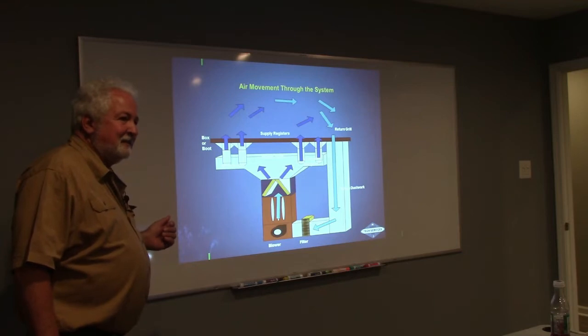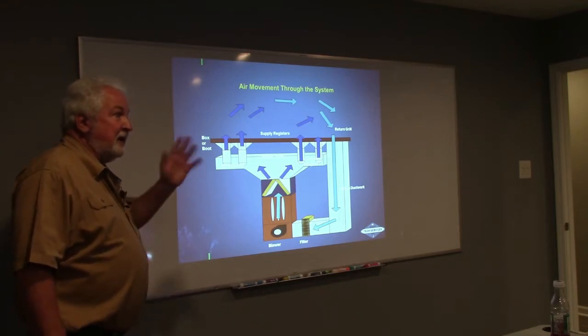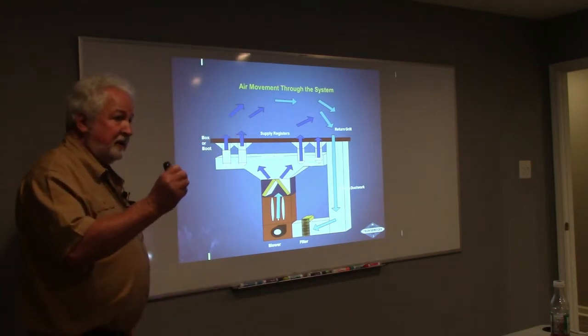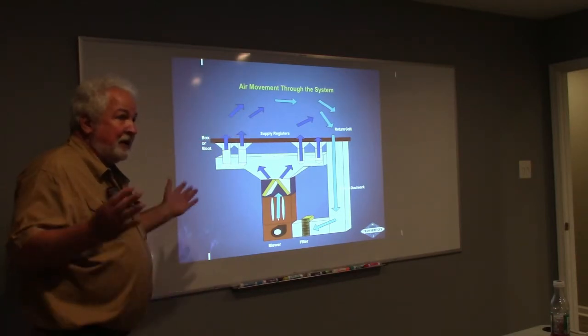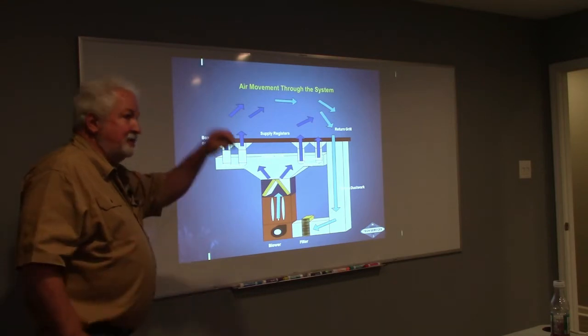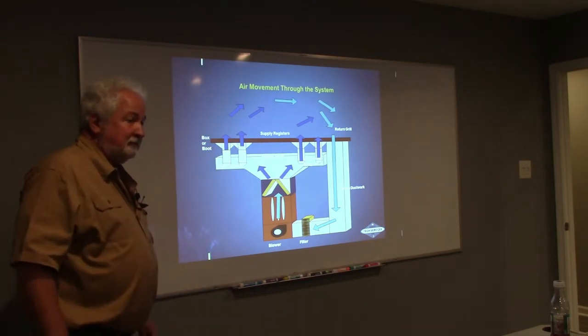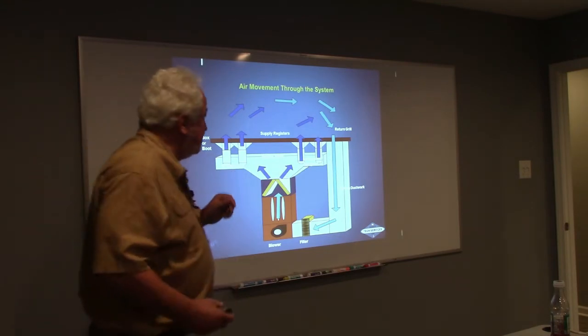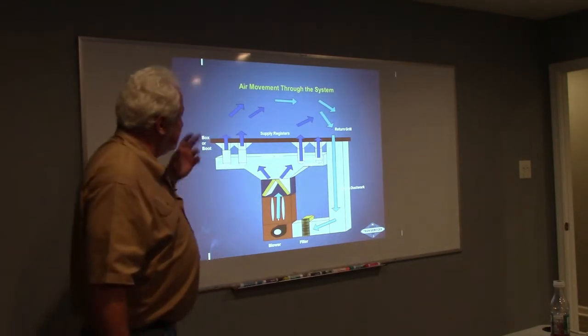We normally all do that too, wherever the airflow is. My guys did, the wing nut was on the top and on the right side. That way, anytime my guys went back on a call, they knew where the adjustment was, on the right side or on top. You didn't have to start cutting the whole duct trying to figure out where it was. It was right there.